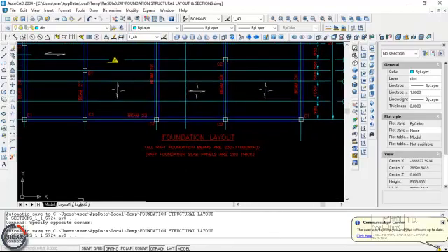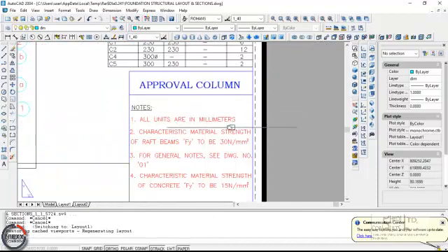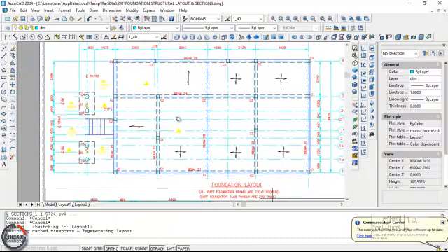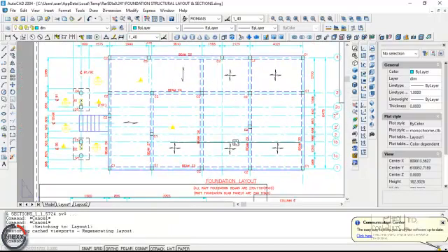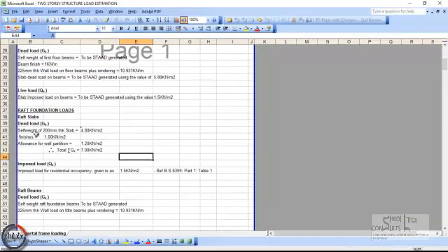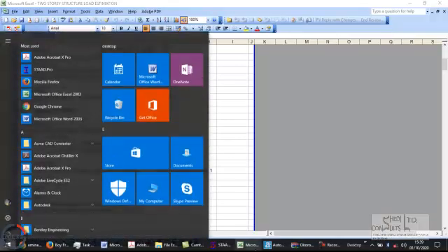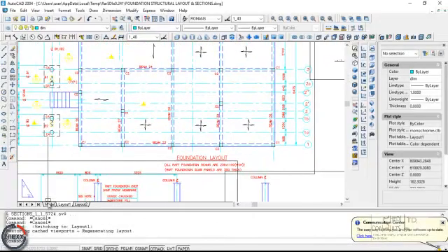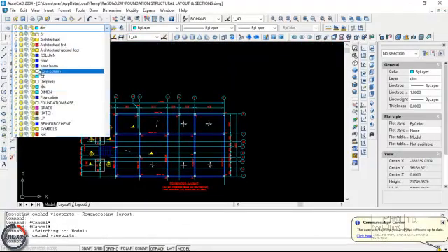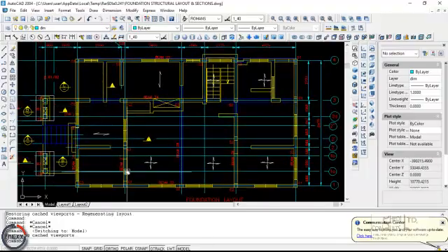So all units are in millimeters. When we say 200, we mean that it's in millimeters. The drawing has to be very detailed so that whoever is reading the drawing can implement carefully on site. So we look very carefully. The thickness is 200, so the self-weight of the raft slab is 24 times that thickness, which is 4.8. The finishes: if you look at the structure, you have architectural elements, you have the block work, and so you have the block work within the slab panels.